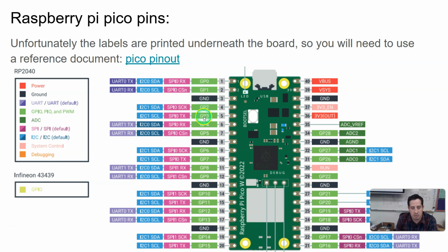What that means is that these pins can be used for a lot of different things. That's what general purpose means. They can be used as inputs and outputs. We can use them to control things, which would be setting them as outputs, or use them to get information. We can check to see if they're connected to the high voltage or the low voltage, and that would be using them as an input. If you want to do more reading beyond just whether it's connected to high or low voltage, we can use these analog inputs that we only have 3 of here.